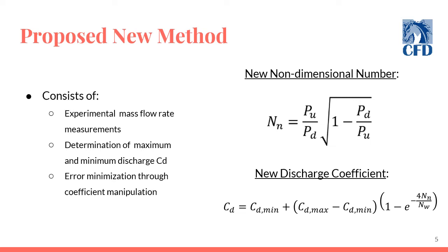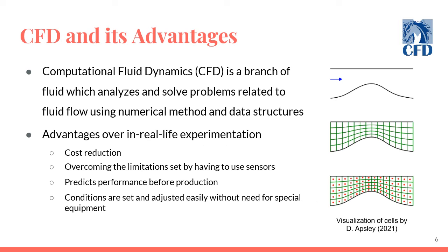To acquire this experimental data, we use CFD software, specifically ANSYS Fluent. Computational fluid dynamics refers to a branch of fluid flow study that uses numerical analysis and data structures. The flow's domain is divided into fine segments called nodes and elements over which fundamental fluid flow equations are solved, allowing for a complete knowledge base of the flow's behavior given a set of conditions.